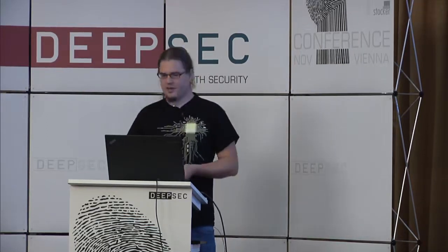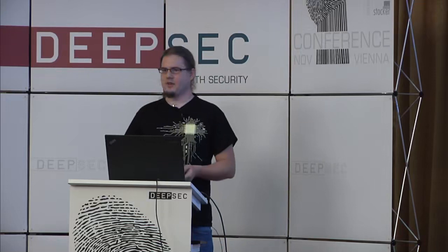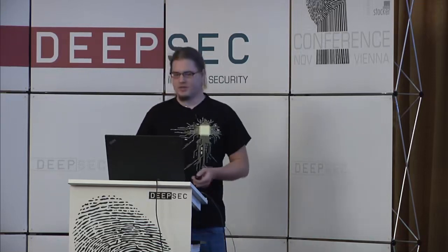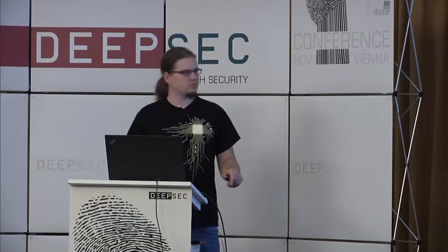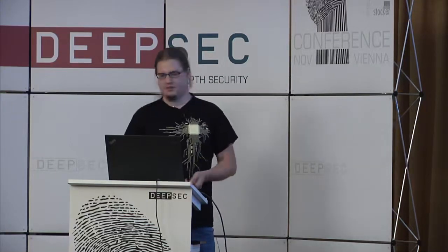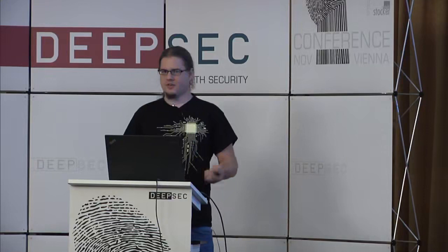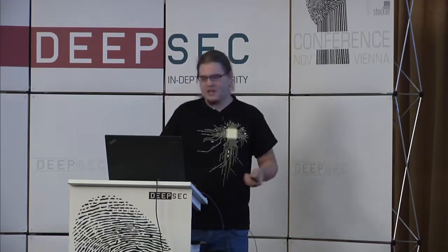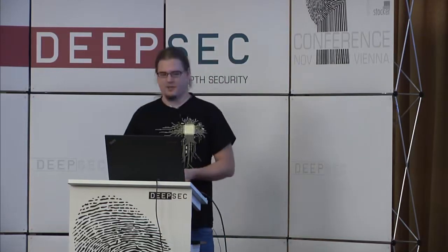And concerning the replay attack, they say they try to fix this in this product and also in future products. For the current product, I don't know why they're trying to investigate how they can fix it, because they use a one-time programmable chip. So there should not be any way to fix it, because you cannot update the firmware on that.